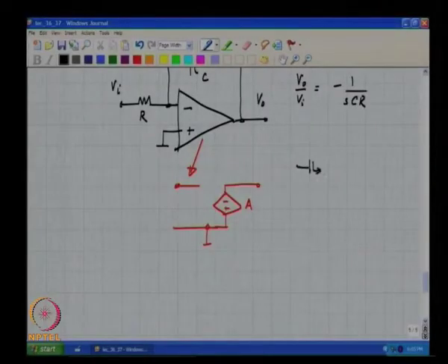With a source follower, the output voltage is one threshold voltage plus one overdrive below the input, which means that on the lower side the output voltage can go almost to the negative rail.